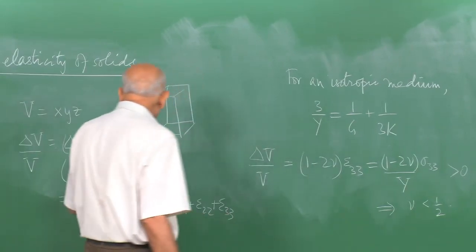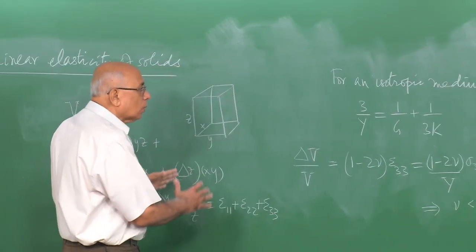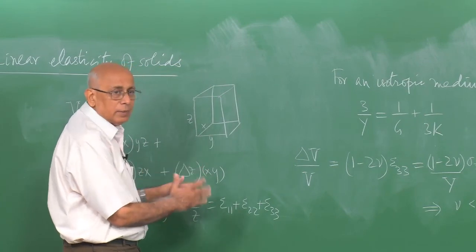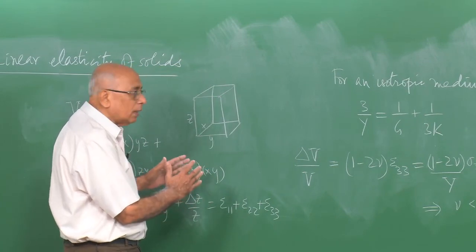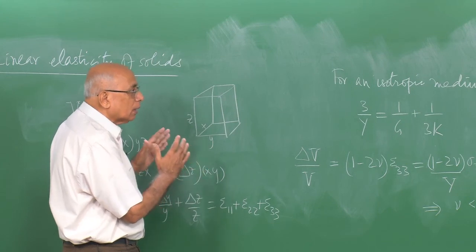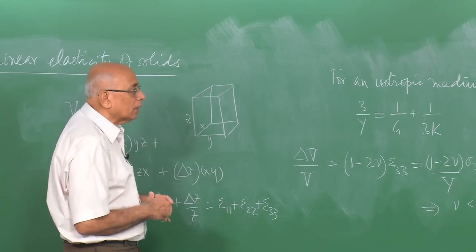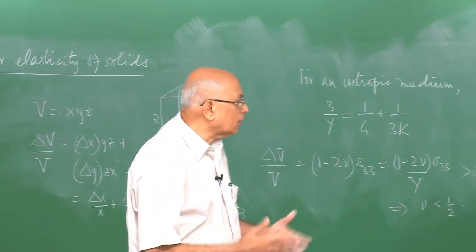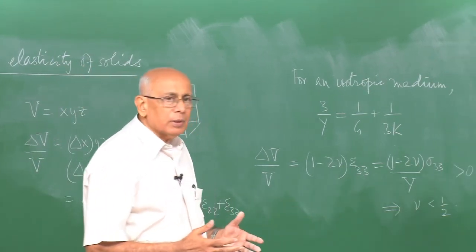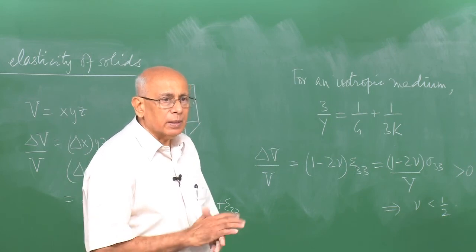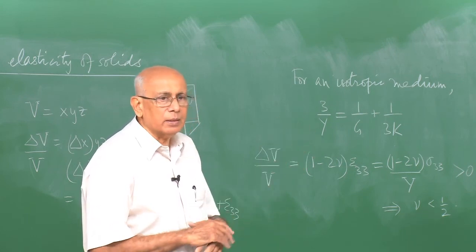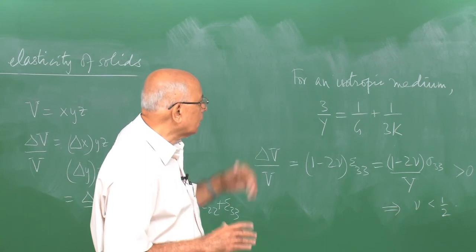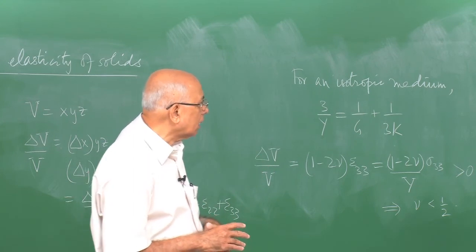On the other hand, I should immediately say that this is only in the elastic region, and only in the case of instant response, completely reversible time independent response. And in real materials, when the stress becomes sufficiently large, you end up with the region of permanent deformation, and that arises due to very different mechanisms altogether than what elastic deformation arises due to.